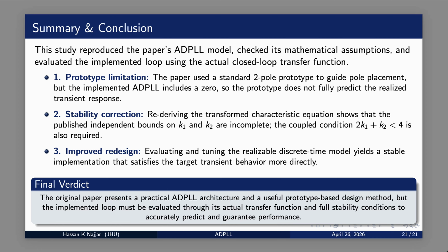A better design workflow is therefore to analyze the actual closed-loop transfer function, derive gains from the realizable model, and then discretize systematically using Tustin or all-zero matching techniques rather than relying only on a prototype that does not fully capture the implemented loop.